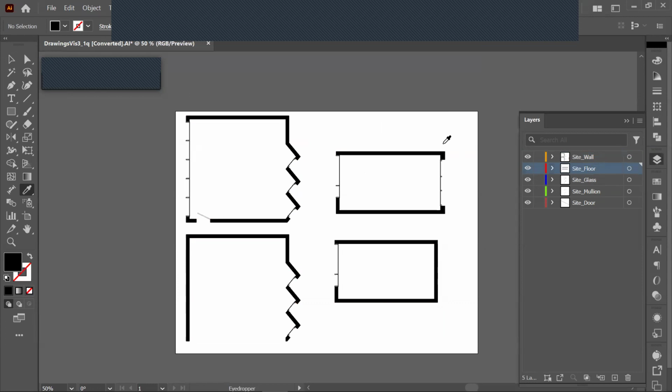Here we can bring, we saw how to get silhouettes of people, so we can do those things. Now this doesn't show any projection, so it's just the simplest type of plan that you can get, but it's good if you want to do a clean abstract plan. It's a fantastic way to go about it. Okay. Again, these work because they're closed polylines. So if you're not, you're going to use the live paint bucket as we have done. Select the lines so they get together, and then you paint inside of each of the set of lines.